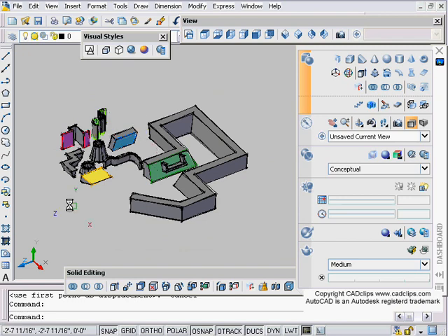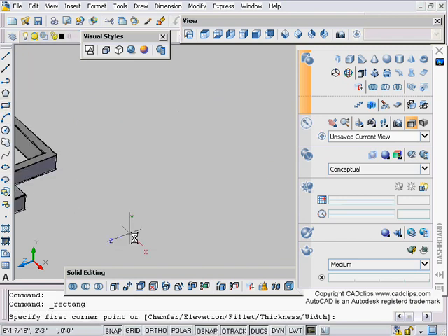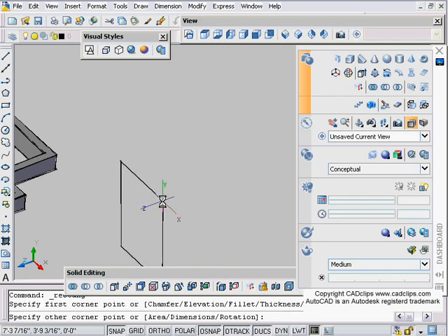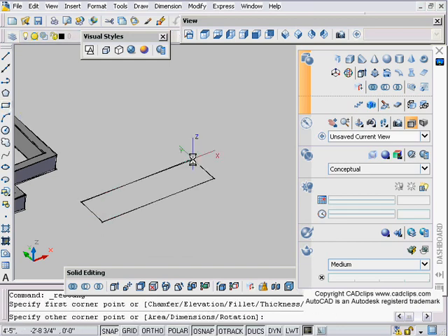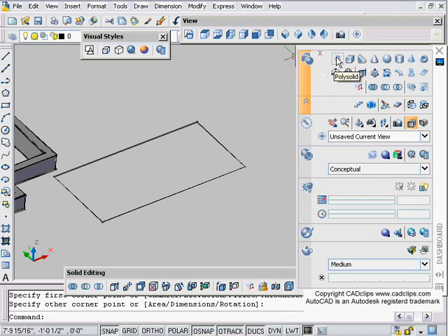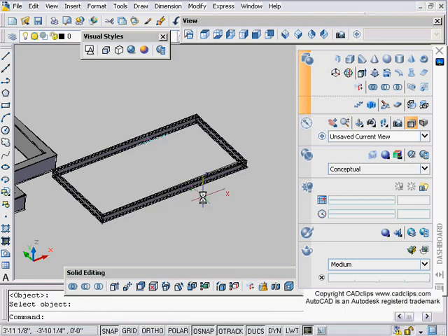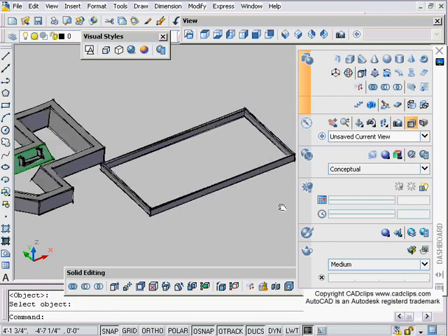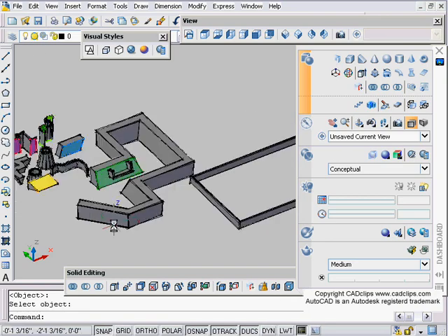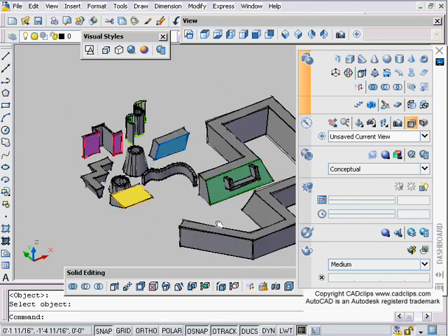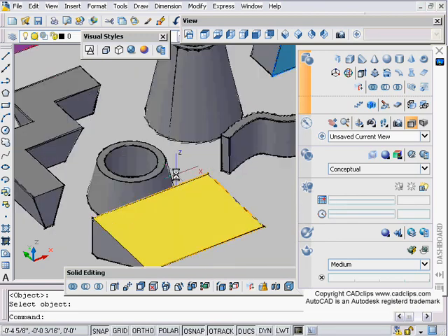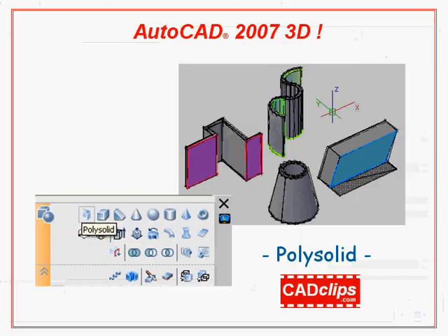Have a look at your command line, convert existing geometry lines. I would go in and maybe try some more of these shapes. Very quickly, it'd be easy to go in and, you know, make a rectangle. Oh, let's do UCS world. That's probably my problem. Make a rectangle box, pick on my Polysolid, enter, pick on here, and you're done. Then you can use your stretch command, instant walls, I guess you could say at least, and then go in and have a look with your grips and have some fun with them. They're not hard to use.